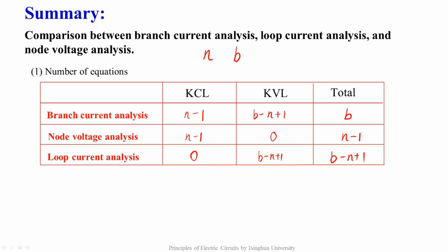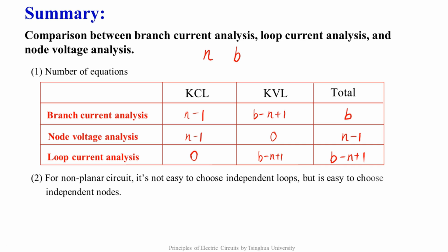After knowing the number of equations required by each kind of analysis, we should make a reasonable choice when analyzing complicated circuits. Reduce the number of equations as much as possible so as to simplify the solution. Secondly, for a non-planar circuit, it is easy to choose the independent nodes because except the selected reference node, the remaining n-1 nodes are a set of independent nodes.